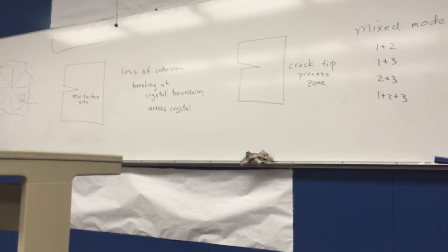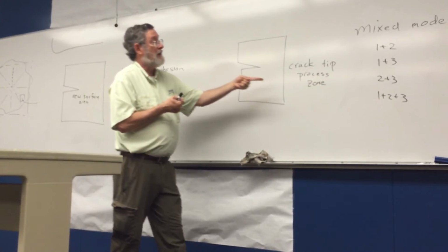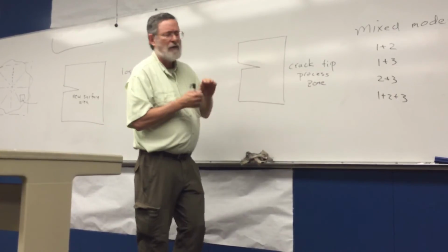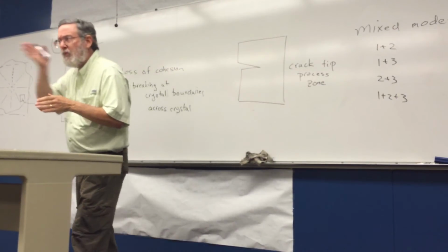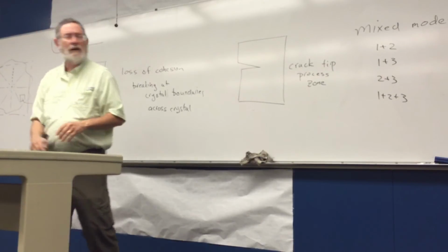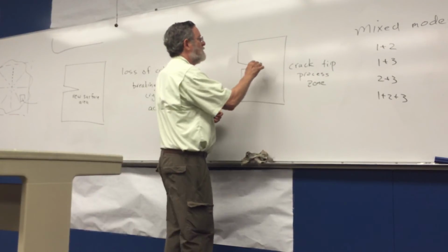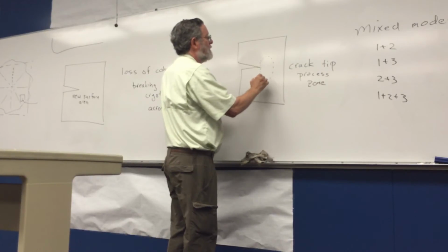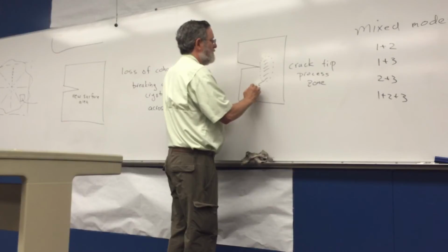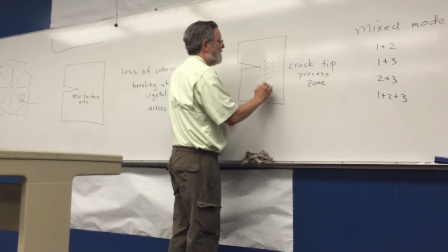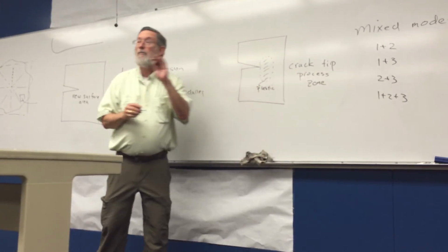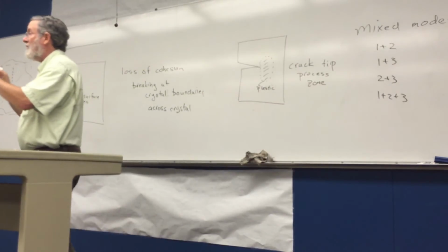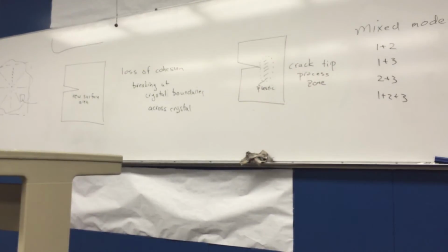I'm enhancing the stress field by quite a bit. So the things that can happen is I can deform brittly, just this one fracture and zoom, it propagates out. I can cause a zone of plastic deformation, so that this would be a zone of plastic yield before the flaw propagates. So that's going to burn up some energy, and the flaw won't propagate as far in the system.